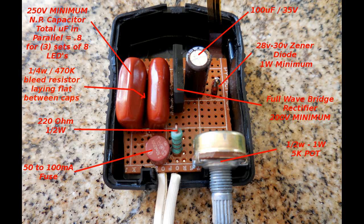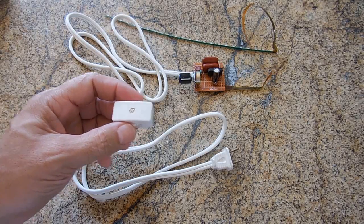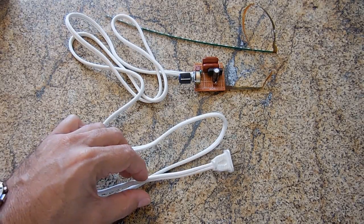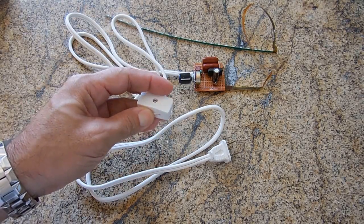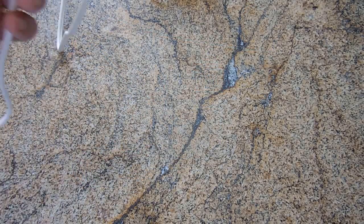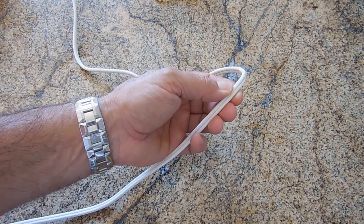The last thing I would like to do is show you how simple it is to add a line switch to your AC power cord. Connecting a line switch like you see here to a 120 volt polarized power cord is very simple. You're going to look for the section of the cord that's going to be easily accessible so you can easily turn on and off the LED light. For my LED light, I decided this area of the power cord is where I would like to place the switch.